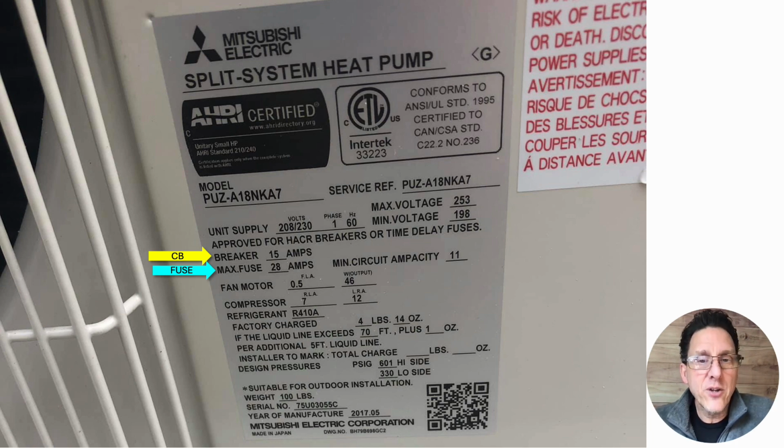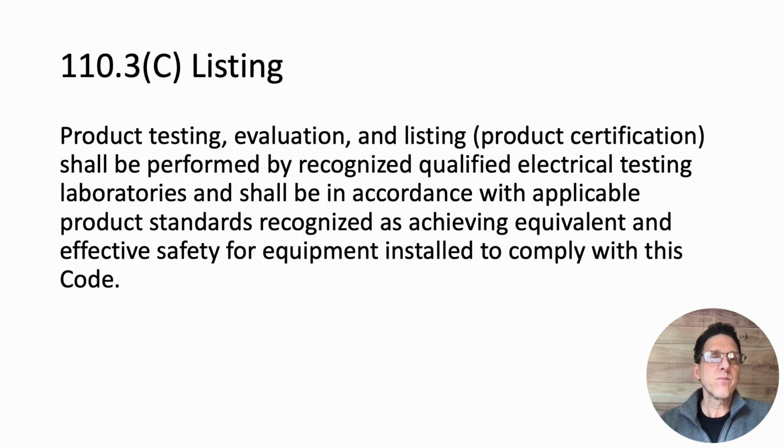Now let's take a look at 110.3(C). As far as the listing, right, these testing labs, who's going to evaluate these products? Well, the code says product testing, evaluation, and listing, or product certification, shall be performed by a recognized, qualified electrical testing lab and shall be in accordance with applicable product standards, right? Recognized as achieving equivalent and effective safety for equipment installed to comply with this code. Now, the NEC does not say which labs, right? However, there is an informational note